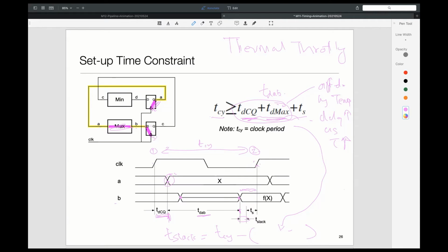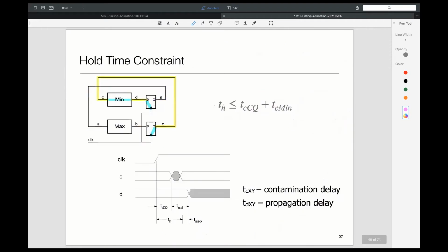So you react to it by bringing down the clock rate or improving the cooling system, which means turning up the fan speed. If you have a PC and you go to the BIOS, you would see that you have all this control over the different fans that your system has. So the heart of it is this issue. The good part here is that I can deal with violations of setup time by slowing down the clock. Unfortunately, for the next one, we are not so lucky.